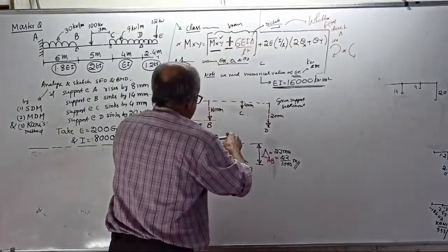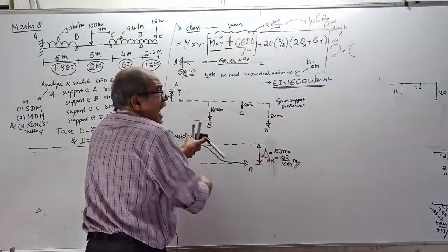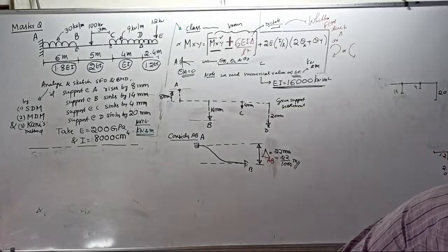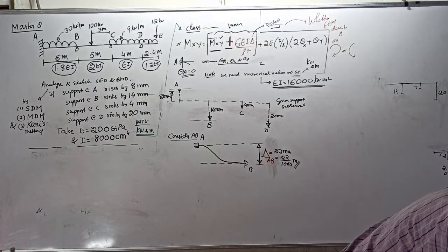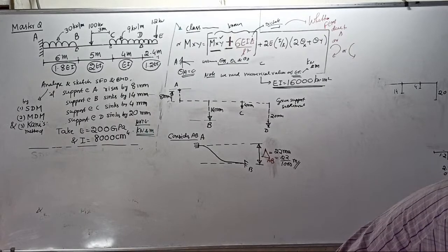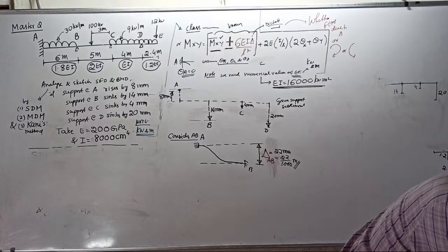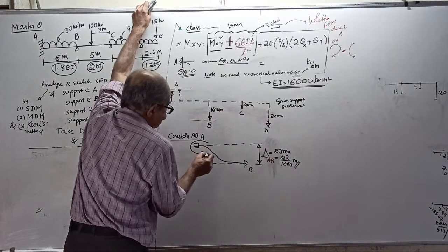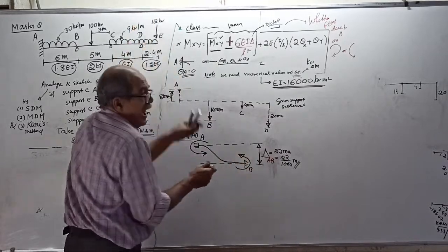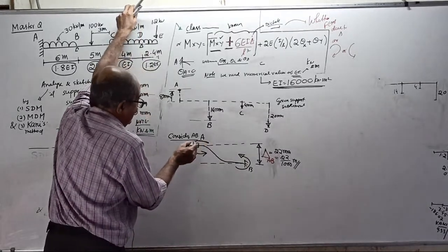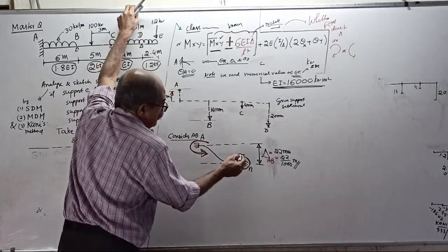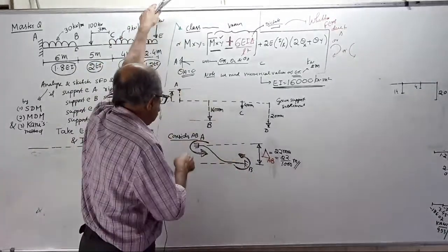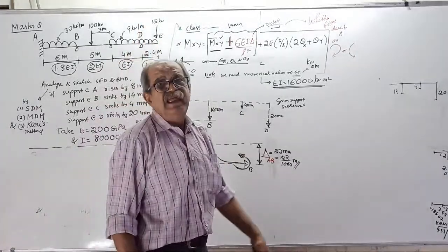Tell me here. If it comes this way, do you require anti-clockwise or clockwise? Easy method. Refer back. Tell me. Anti-clockwise or clockwise? Earlier thoroughly told. I am wasting time explaining this. Anti-clockwise. Someone will ask you, why anti-clockwise? I will tell him, go back to the earlier class and decide and come back. See, red color. Anti-clockwise. This also anti-clockwise. If it is the SD method, that's all. If it is the MD method, you write the formula here. How much? 6EI delta by L square.